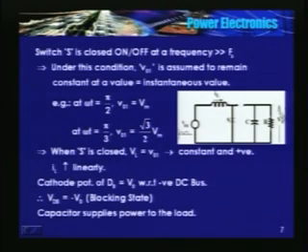Now I might have said that the output voltage will remain constant, and you may say that now the capacitor is supplying power, so definitely the output voltage will fall. Let me tell you one thing: this switch is closed for a very small duration and then it is opened, and the stored energy in the inductor is transferred to the capacitor and the load. This process takes place a large number of times. So though the capacitor is supplying power when the switch is on, I am assuming that VO will remain practically constant.